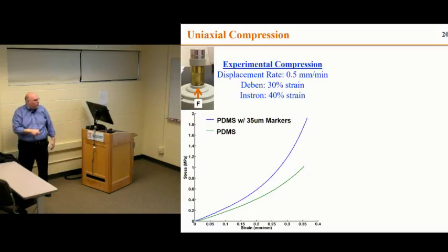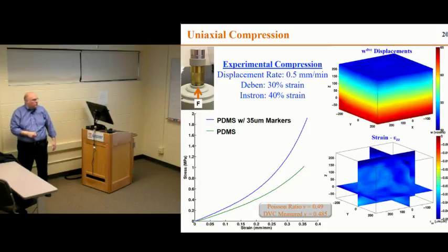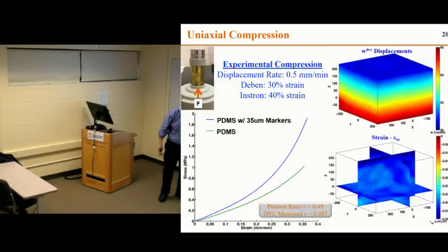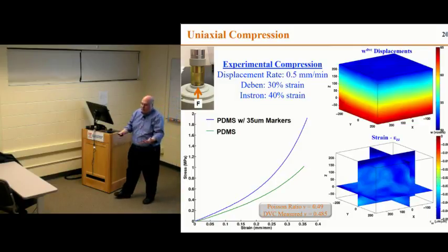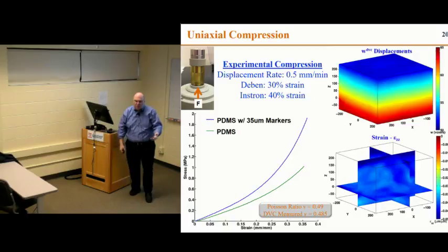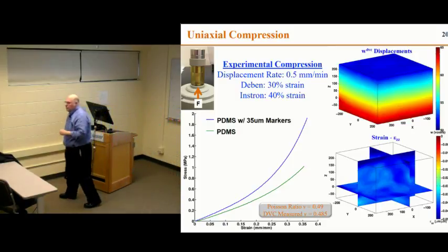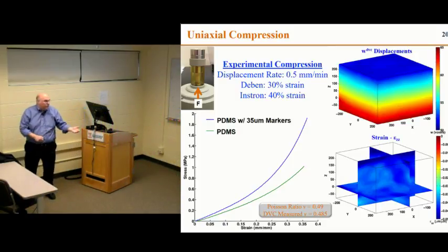And on this material, here's results of a uniaxial tension test. This is the vertical displacement W, so in the direction of loading. It's basically straight uniform contours all around, exactly as it should be. Strain is uniform all around, right? So these strain plots, and you're going to see a bunch of these types of plots from now on. These are basically slices. When you have very large amounts of 3D data, like finite elements, one of the problems is how do you display it, right, to be able to tell a story. So you'll see plots like this where you have these slices along three directions that give you some flavor of what's inside. And here, the field is uniform, so it's all blue, more or less constant strain.